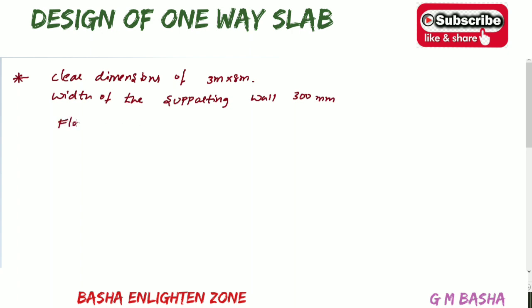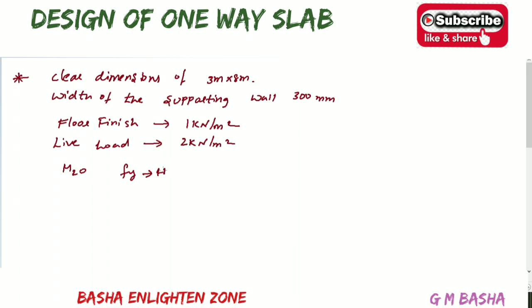The weight of the weathering course over the slab, that is floor finish, is 1 kilonewton per meter square. Take the live load of 2 kilonewton per meter square over the slab. Design the slab using M20 grade concrete and HYSD bars. So there will be HYSD 415 and 500, and we are considering Fe 415 bars. Check the design for stiffness.